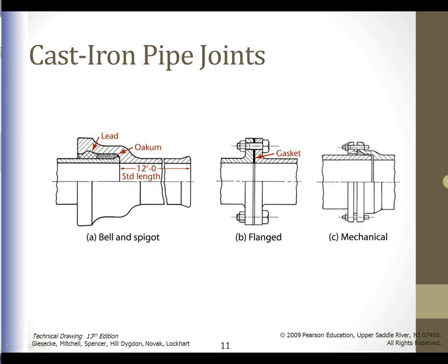Now, when you're talking about soil pipes, you're talking about 3 inches to 15-inch diameters and a standard length of 5 feet. Designers have to consider the internal pressure and the external load of these types of pipes in addition. Cast iron is brittle and when settling in the earth may cause the pipe to crack and break. Now, see figures 21.8 and 21.9 in your book for illustrations, and Appendix 38 for various classes and pressure ratings of these pipes.